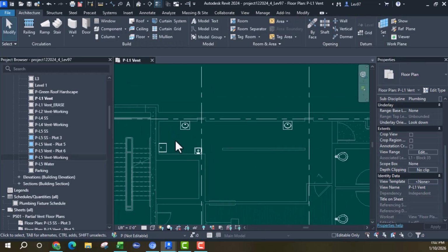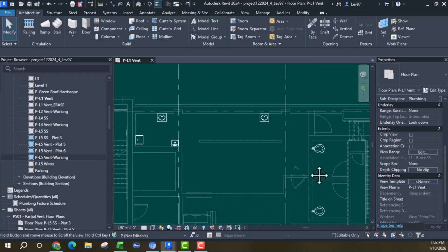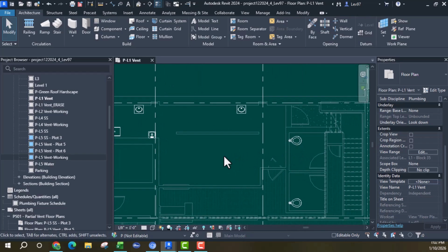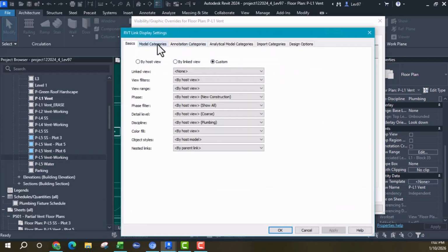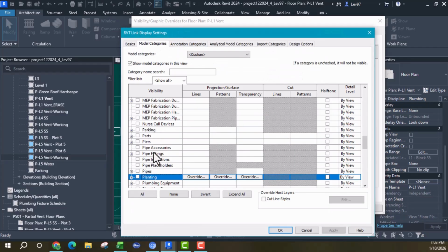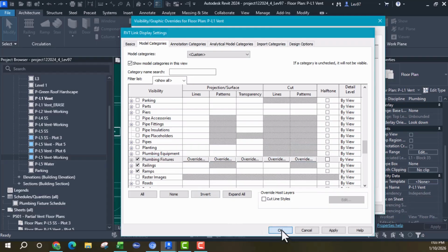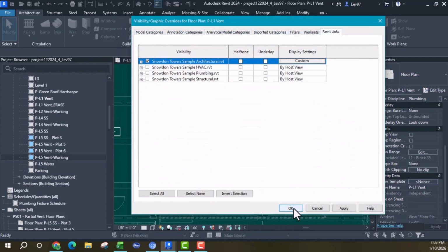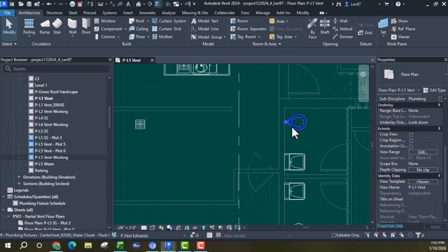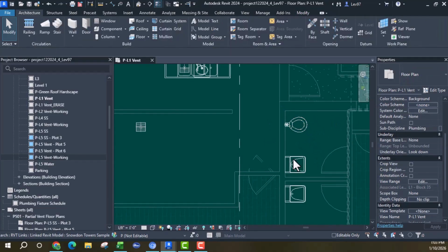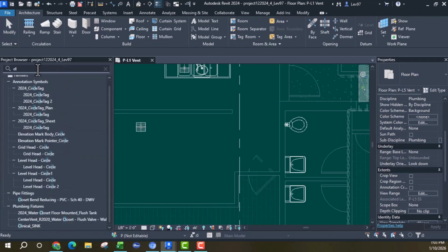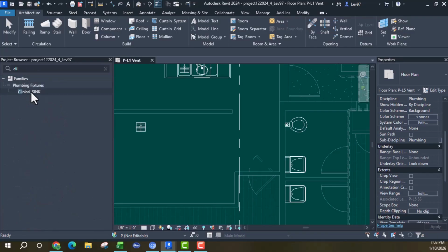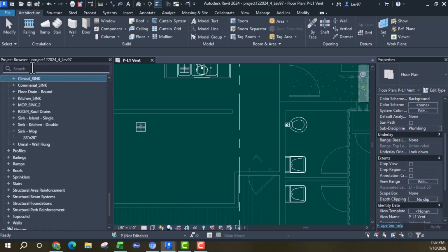So all of these placements are with the architect. And there's a couple of sinks down here. Let me turn on the fixture units. Plumbing fixture, type PL, and go down for these plumbing fixtures, because I know that there are sinks here. And this is mine. This is mine, and I need a sink. That is a clinical sink. So I'm going to type CLI.